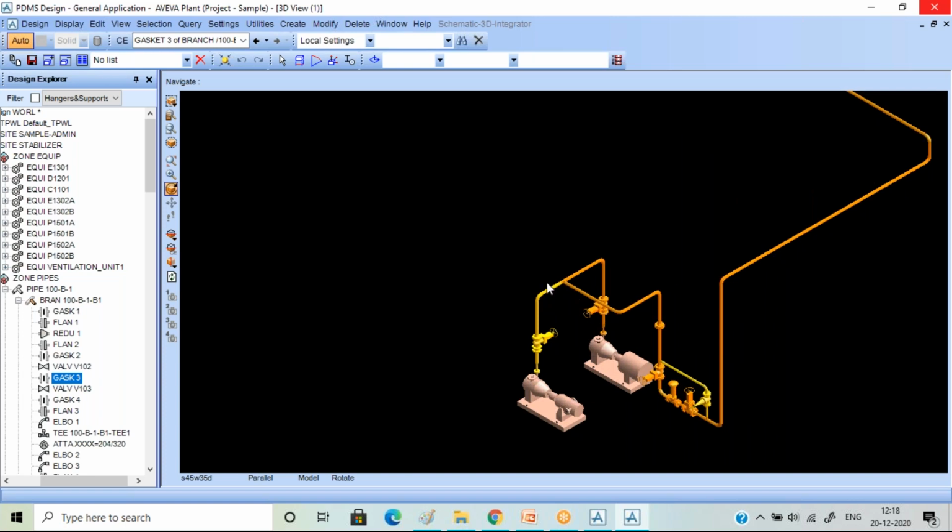So obviously this particular section, this is your upstream line, this is a downstream line. Again, downstream and upstream, say there's an orifice, how your orifice has to be modeled, what amount of distance, 15D and 5D in the upstream and the downstream, how you're supposed to maintain that distance. That section will be explained very well. Okay, now we go on to the remaining part.